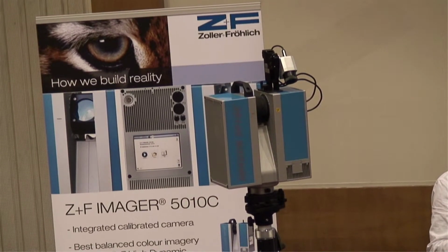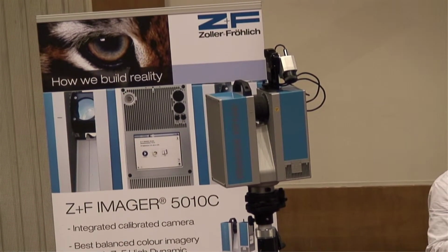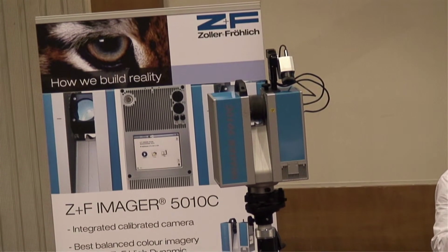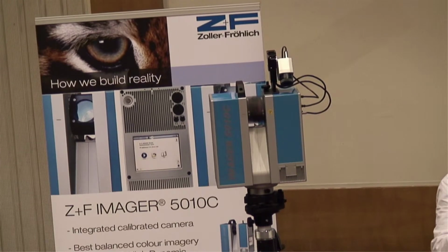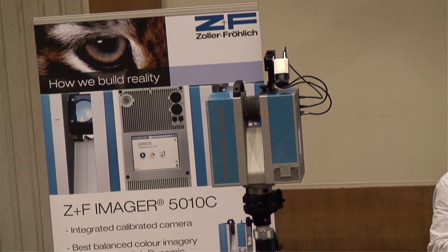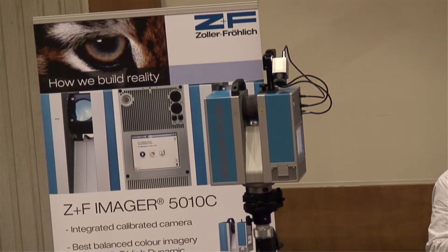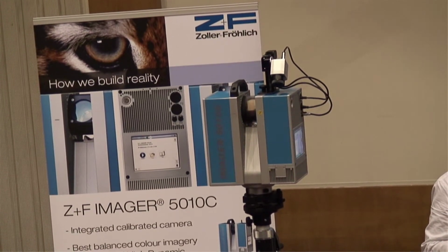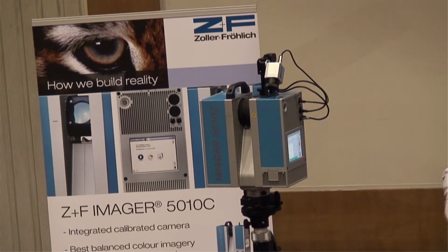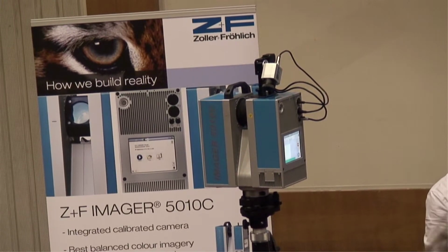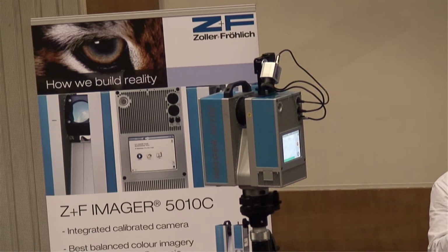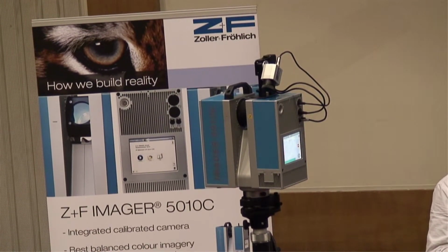Also, if there are cracks in the wall below 3 millimeters, the laser beam does not get inside these cracks. It gets split. You can probably see on the intensity that there is a crack, but you cannot acquire the geometry, even if you increase resolution. It disturbs as a line, and you can maybe detect that there is a crack, but you cannot really measure it because it is the limit of your technology.